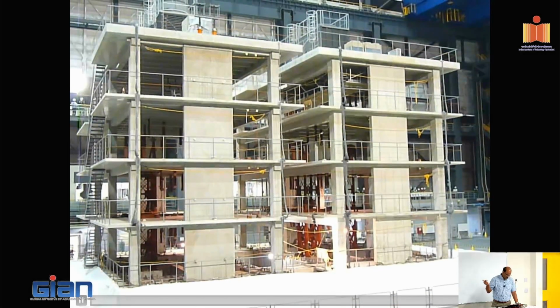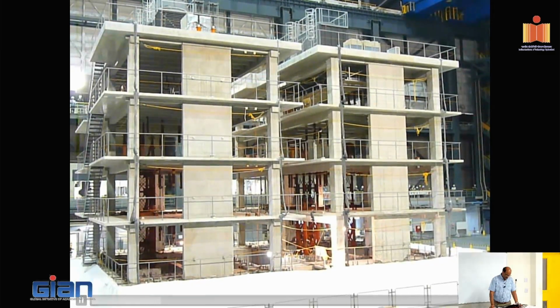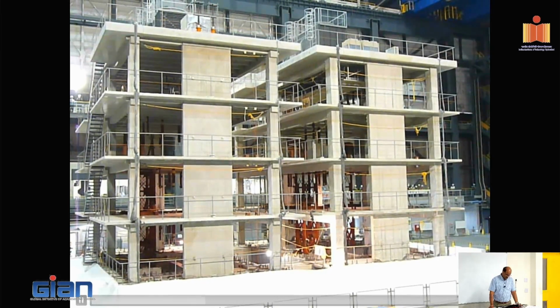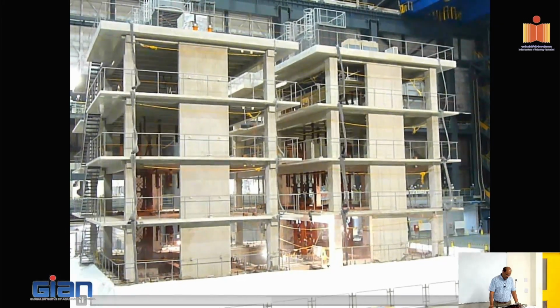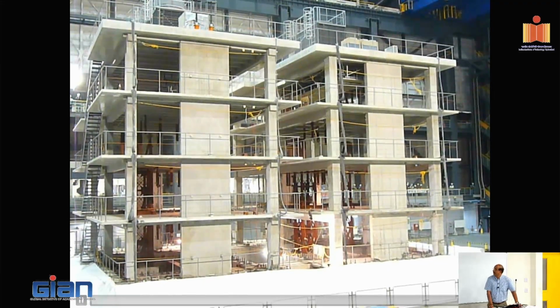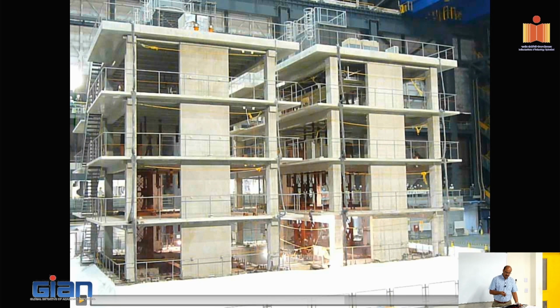So this is another test. One of the things they observed in this test was that this hinge formed, and because of the hinge formation and significant amount of inelastic action, this wall was actually sliding at the base.